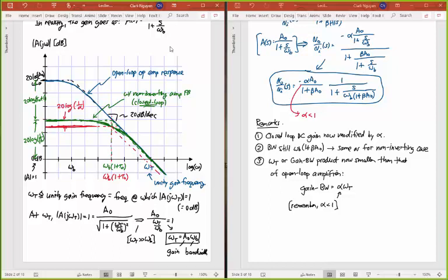And what you're seeing here is that its asymptote, the whole curve, is now below the green curve, which was the curve for the non-inverting amplifier. Okay, so the red curve that I have right here is this same op amp, the same op amp in blue that I'm showing here, except now with non-inverting amplifier resistors, same resistors as I use for the inverting amplifier. But when I have inverting amplifier feedback, I get the red curve when I close the loop. So this is an example of another closed loop transfer function. I've closed that loop, but now I have less gain and I have a smaller 3 dB bandwidth. Okay, that means my gain bandwidth product is smaller than it was for the non-inverting case and for the op amp itself. Right? This is now the omega t for the inverting amplifier case.